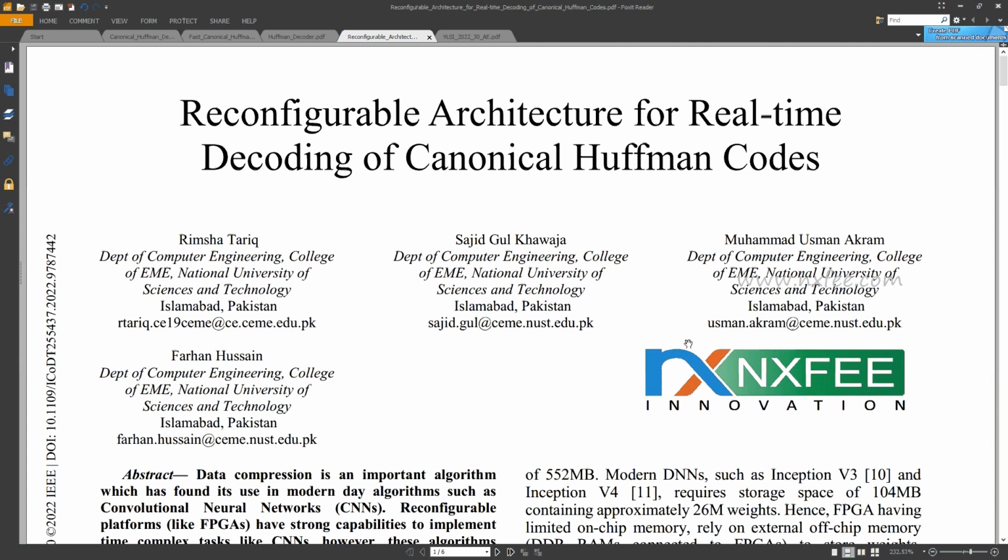In this case, the Huffman machine presents a lossless, low-memory configuration, and it supports multi-bit operations for data compression and decompression. This technique takes an input of 640 data bits and produces a compressed output of 90 data bits using the variable-length canonical Huffman encoding method. The same 90 data bits are then taken as input and decompressed to 640 data bits using the canonical Huffman decoding method. Finally, this work is presented in Verilog HDL and synthesized on a Virtex 5 FPGA, with results in terms of area, delay and power.